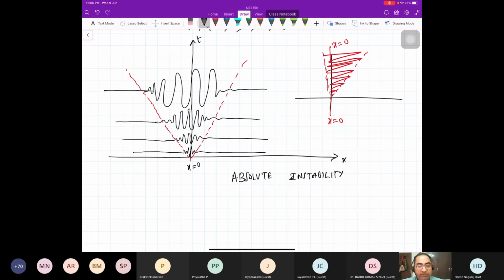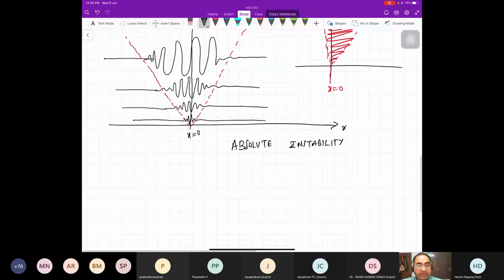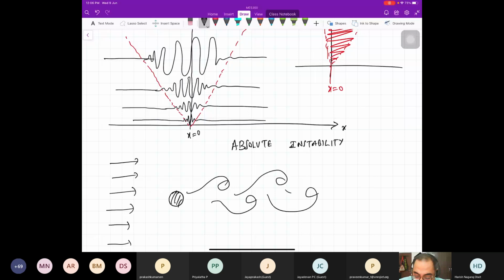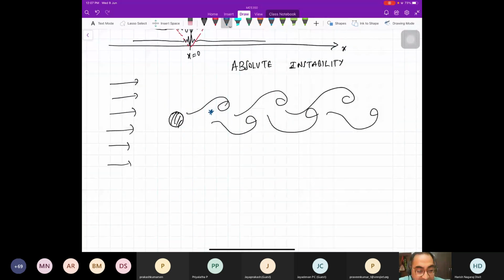For the vortex shedding instability, the von Karman vortex street, here is a body, and here you have a mean flow. If you remember, we saw images like this. Now, if you take a pressure probe at this location and plot how the velocity, vorticity or pressure at that point looks, it's very easy to get pressure probes. You will see that the pressure will be nicely oscillating.